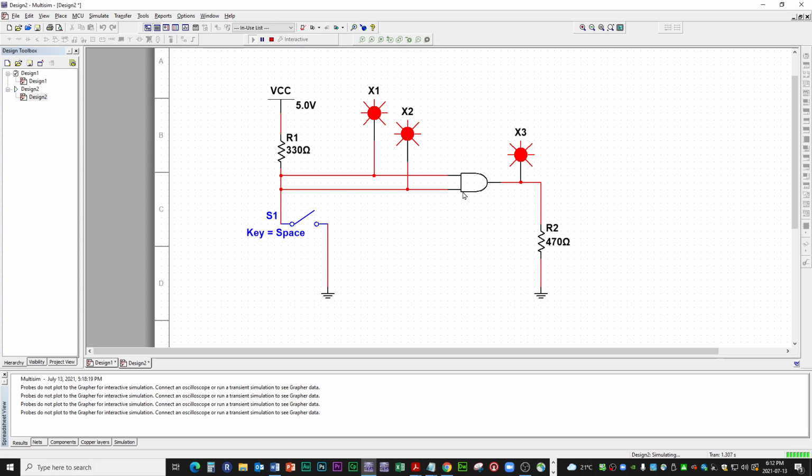Why not? It's an AND gate, so the switch is open. So that point here is pulled up high. So we got high here, you got high here. 1, 1, 1. And 1 gives you 1. Wow, works so far. Let's see what happens when we close the switch. Whoa, we got 0 and 0. We got 0. Nice. Right?